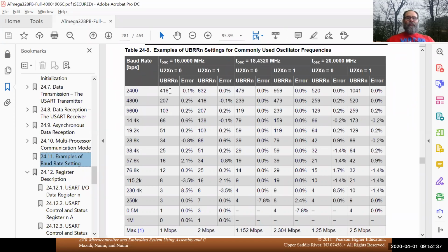So ideally you've got a square wave like this, a square pulse. And ideally you're checking right in the center of that pulse to see whether it's high or low. In the case of, and I may have this backwards, a positive error discrepancy, you're moving this way. In the case of a negative error discrepancy, you're moving that way. And eventually you're going to not be in the proper bit at all. You're either going to be in the bit before or the bit after. And that's the point where you get bad information.